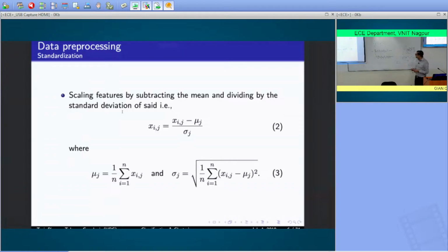And why is this important? Let's say you have some variables that are of the order of 1,000, and other variables that are of the order of 1. An example would be temperatures that are about 1,000 degrees Celsius, and a concentration that is 0.5, and you're trying to build a model. What you will do is take your errors in temperature, let's call it E of t, add it to errors in concentration, and minimize these errors when you build a model. That's what is typically done.